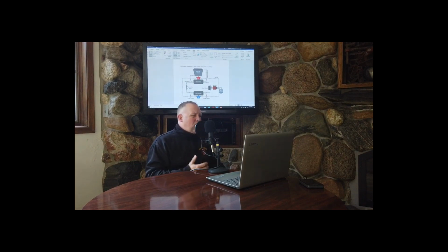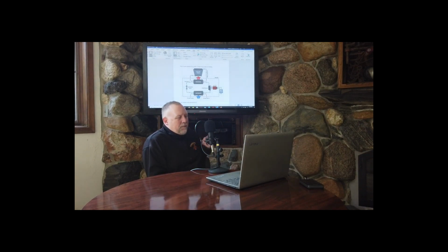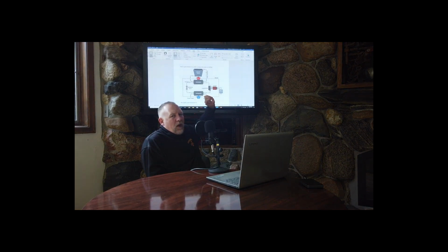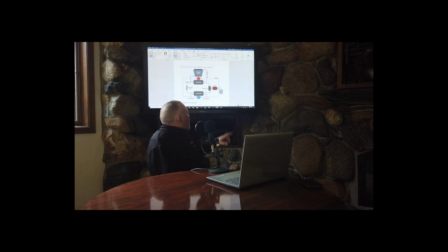Also, in terms of energy efficiency, these are the largest ones in terms of physical size and cooling capacity. They're also the most efficient. If we define efficiency as kilowatts of energy used, kW, per ton of cooling, these bigger ones are going to be the most efficient. I'm transferring energy through an evaporator that is cooled by water. We're also going to have water at the other end here on the condenser side. I'm going to explain that in a little bit.